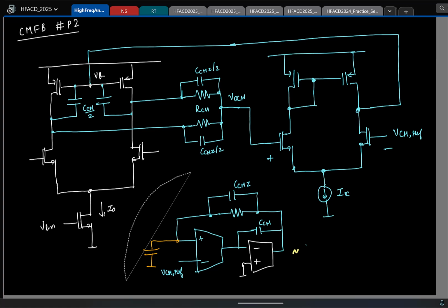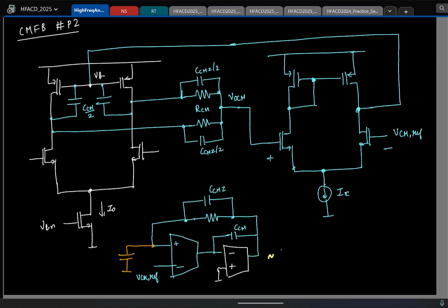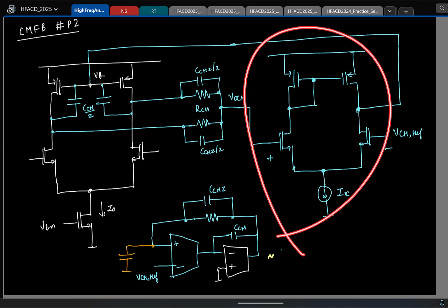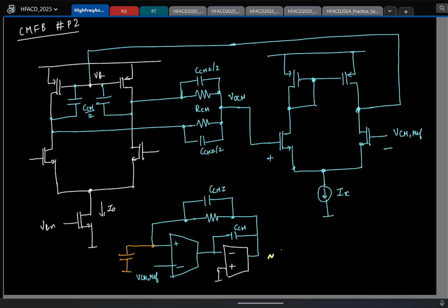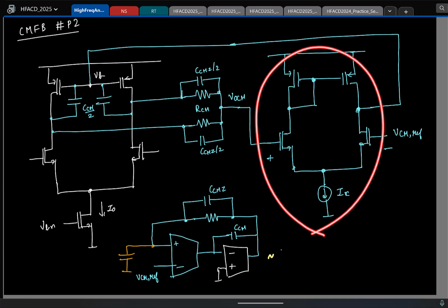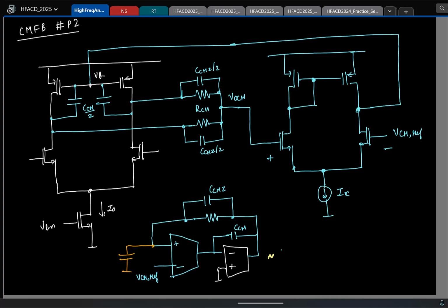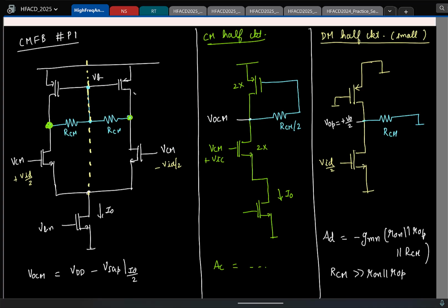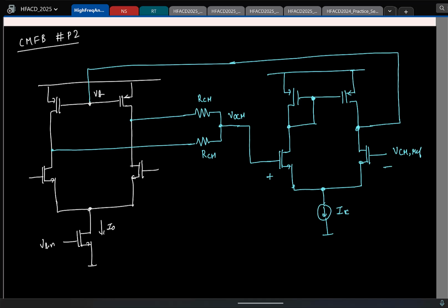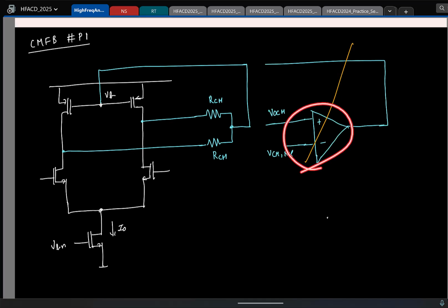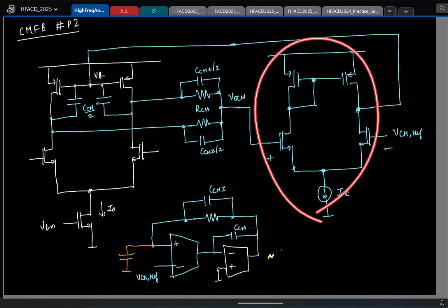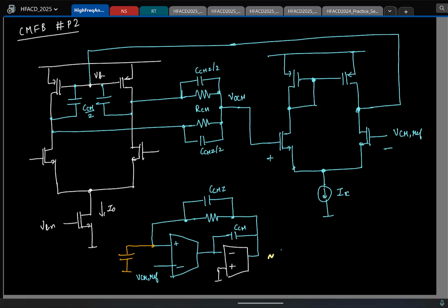Cool. So now a couple of questions to you. See here, all I knew was I wanted to use an op amp, but I have used an NMOS input op amp. Do you think a PMOS input pair would have been a better choice here? Is my question clear? We started off with the fact that we wanted to have an op amp, wherever it is, op amp here, and that op amp, as of now, I have realized using an NMOS input differential pair. Could I have done better with a PMOS input pair or no?